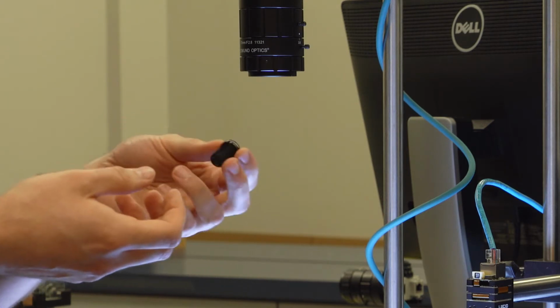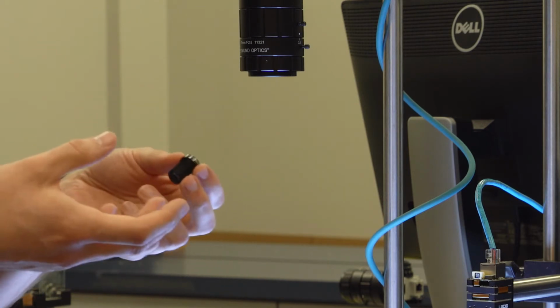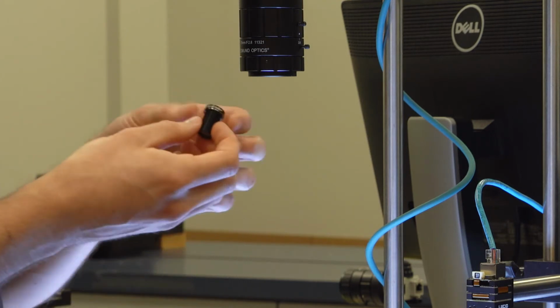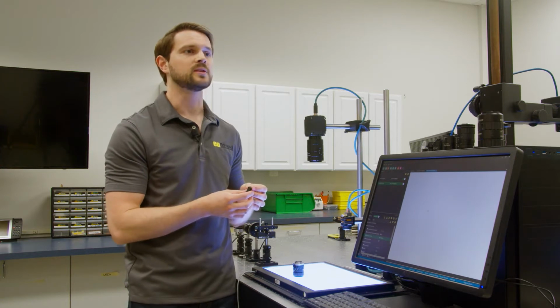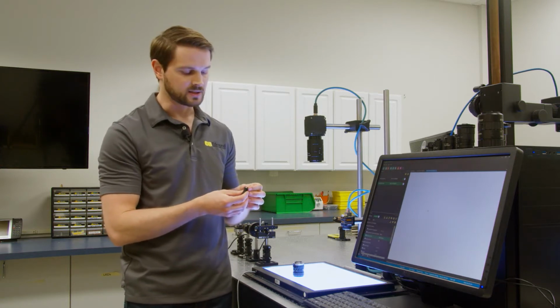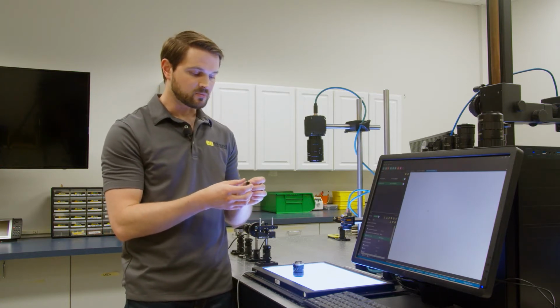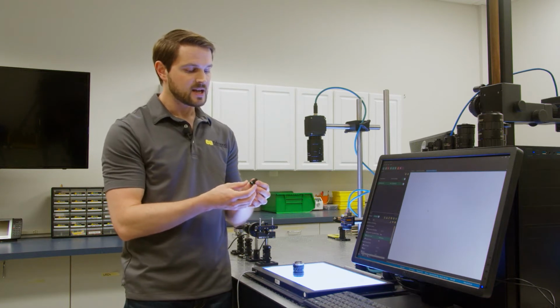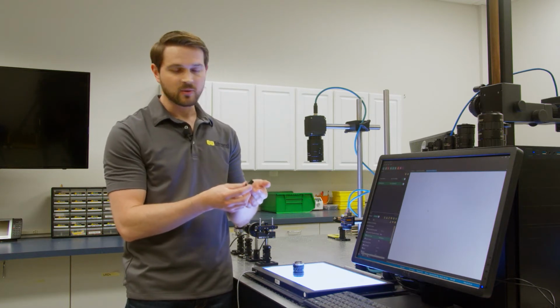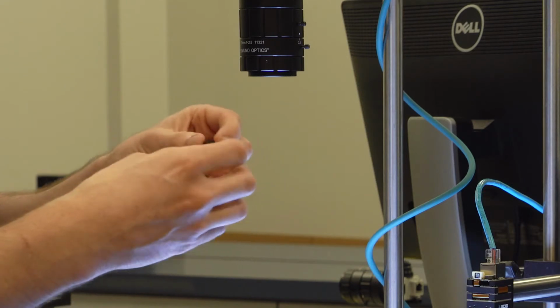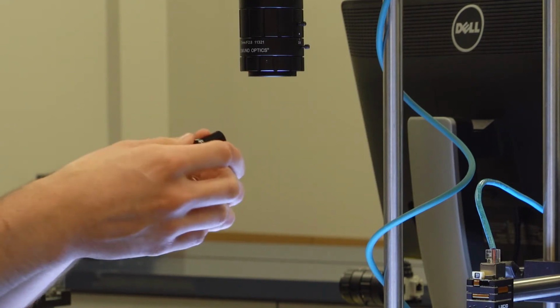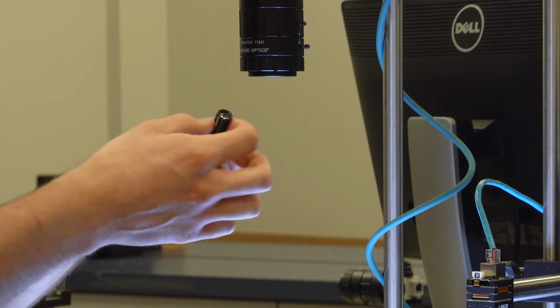These are used for lightweight applications or small applications. Kind of makes sense. It's a small, lightweight lens. So they're used a lot in drones or in document scanners, biometrics, things like this. They're pretty high resolution little guys, but as you can imagine, they're relatively feature simple. They don't have any sort of iris adjustment. You focus them by threading them in and out of their barrel. And there's no real way to lock it down.